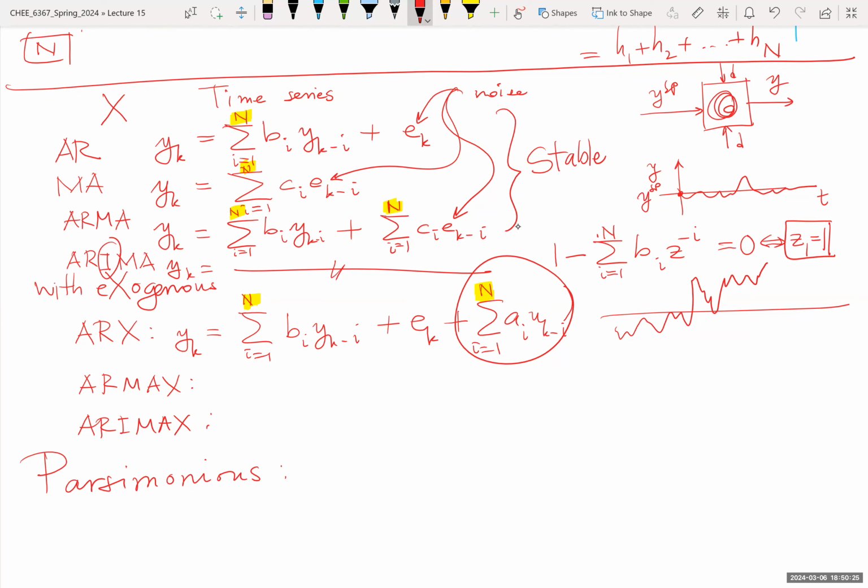Well, a rule of thumb. If you have a cubic polynomial, you need 40, 50, and so forth data points. If you have 40 parameters in an FIR model, you might need 400 data points, which may be too many. So over the years, it's not about computational power, it's about experimental data points.